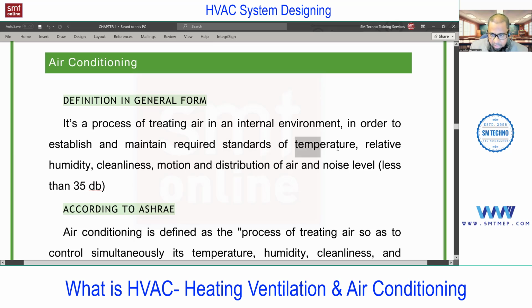of temperature. So we can increase the temperature or we can decrease the temperature as per the requirement, means heating or cooling. Relative humidity, this is important, RH. And if you don't know what is RH, we'll discuss in detail in chapter 4, psychrometry. I'll just give you the idea. If the RH increases above the limit, for example, if the RH level is 70% in the room, you will feel a lot of sweat, and you cannot breathe easy.